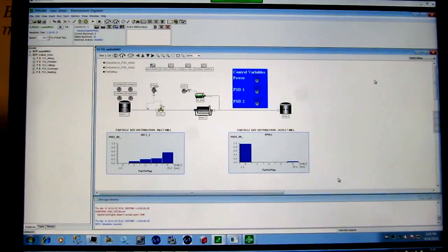That's really important because one of the key things that you do on a site survey is to assess the current status of your normal regulatory control. If there are oscillations in the process, or if there is not really good regulatory control in terms of PID control, and the current status of the plant is not in good condition, then the result of implementing an APC is not really powerful.